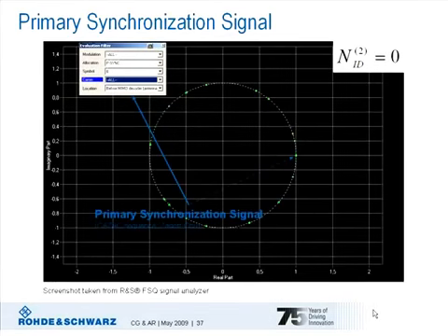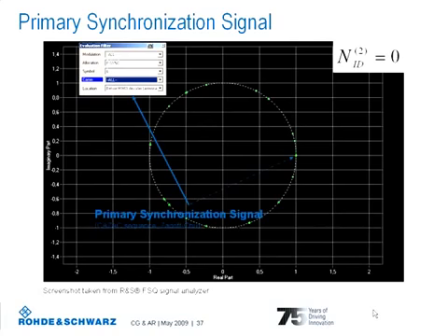Let's look at the two signals now. The type of signal which is used for the primary synchronization signal is a Zadoff-Chu sequence. Zadoff-Chu sequences are CAZAC sequences, where CAZAC stands for constant amplitude, zero autocorrelation, where the name already describes the characteristic of those types of sequences.